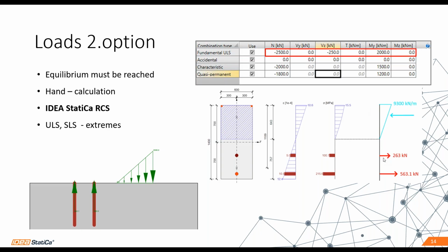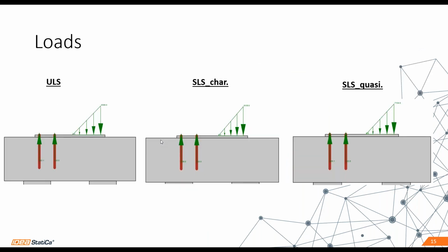So it means you will get the forces in the anchor, and you will also get the stress in the compressed area of the concrete, and from the stress you can derive this load, which will be applied to IDEA StatiCa Detail. Yeah. So this is the option which I prefer right now for putting the forces, and this is how it will look after we jump to the application IDEA StatiCa Detail.